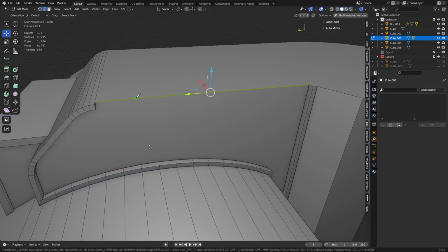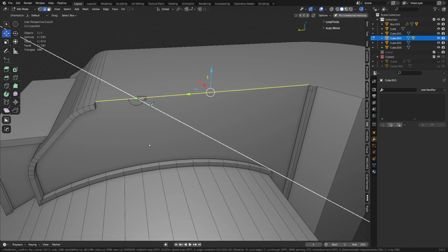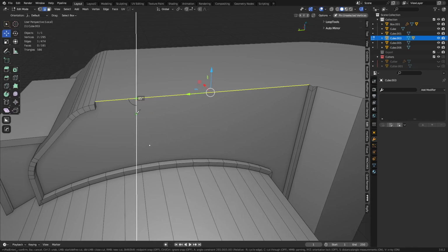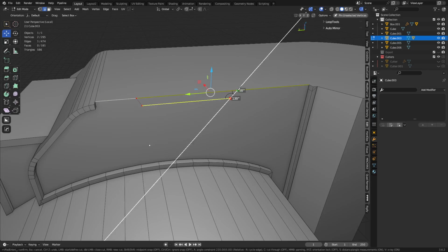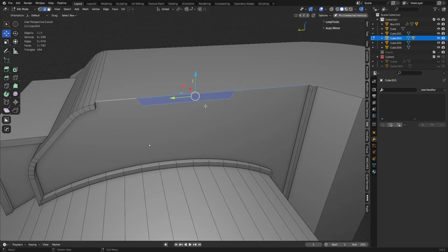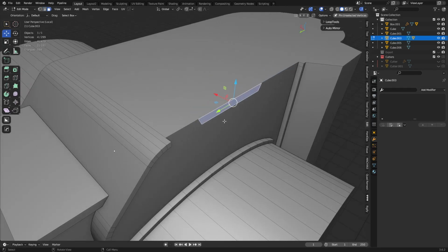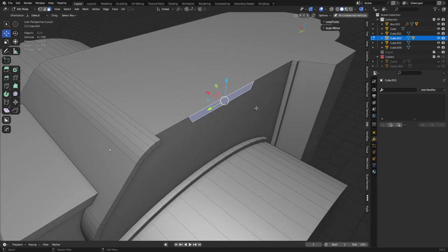But anyways, let's say I wanted to cut here, and I'm going to hit A twice. You can see it lines up to that edge now. So I can actually pick the increment here that I want to rotate. So like 120, I think it's 120 I want, and then we'll go back this way, and we'll try to hit another 120. Okay. Right. If I wanted to take this all the way through the shape, we could do a Boolean with a cube.